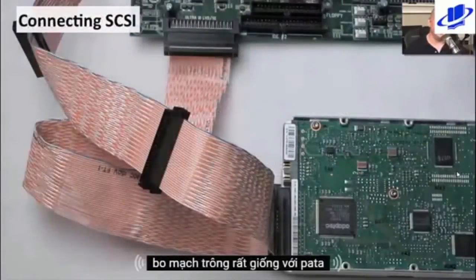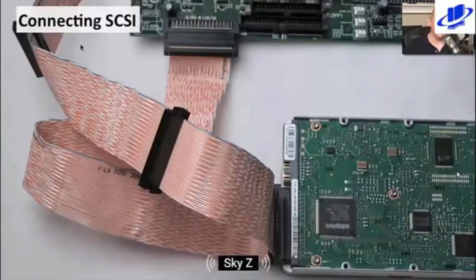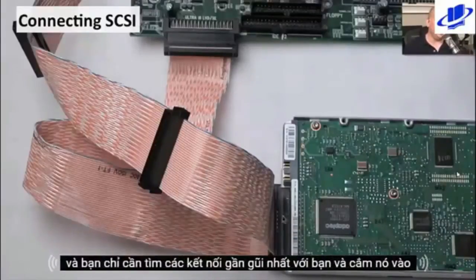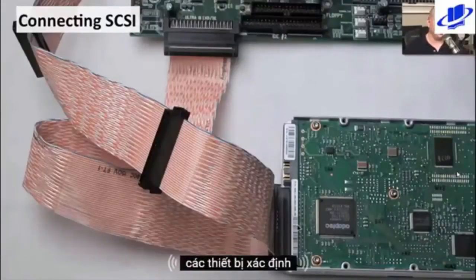The connection of the SCSI device on your motherboard looks very similar to PATA in that we've got a connection on the motherboard and multiple interfaces on SCSI. But of course, with PATA, we are limited to 2 individual devices, whereas with SCSI, especially the wide bus SCSI, I can connect up to 16 devices, and you would simply find the closest connector to you and plug it in. It doesn't matter where along this particular cable we plug in our SCSI device.